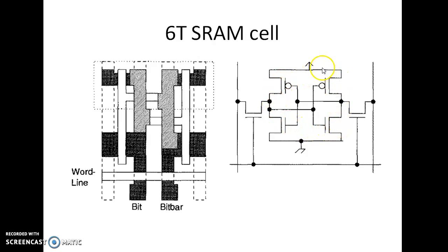Right? And the advantage of CMOS is it has least static power dissipation, because if this is on, this would be off, and vice versa. So there is less chance of a path existing from the supply voltage to the ground. Right? And from the operation point of view, everything is the same.